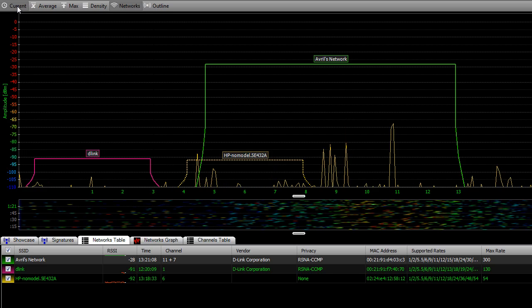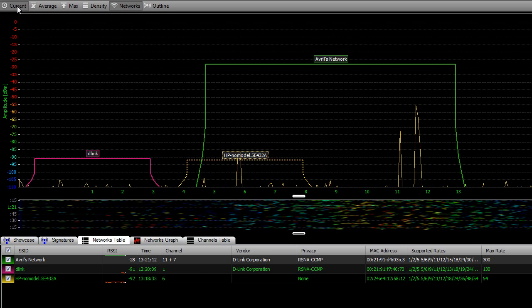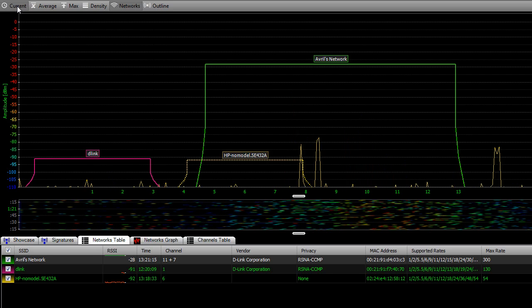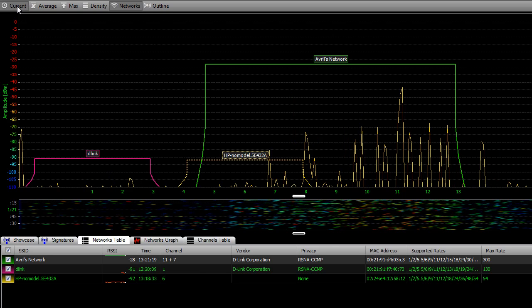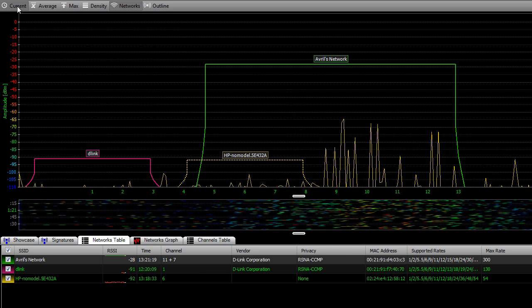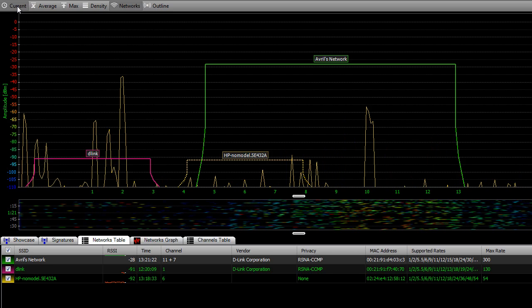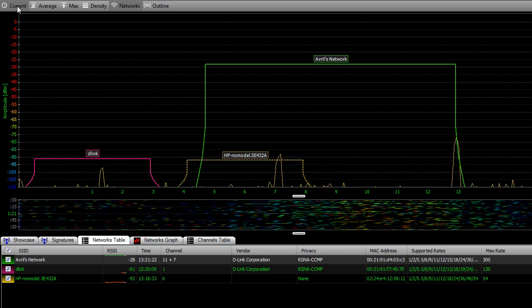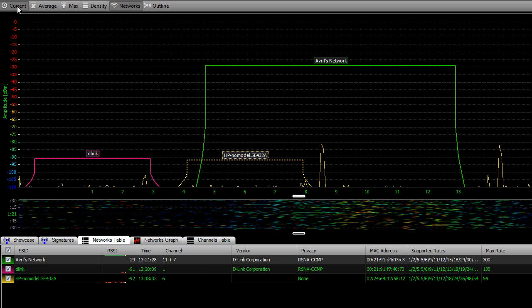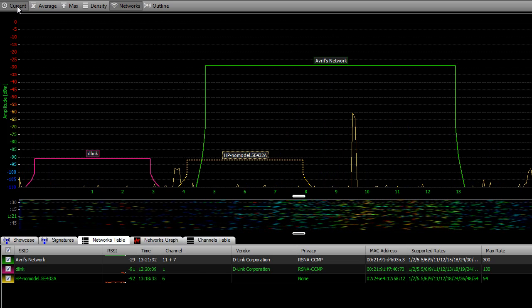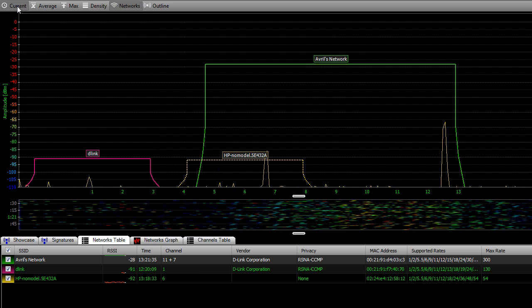Those updates are transmitted from the solar panels to my home wirelessly. As I mentioned, they're using a proprietary system, and this system happens to use the entire 2.4 gigahertz band, and so it's impossible for me to move my wireless LAN to a different channel and avoid that interference.